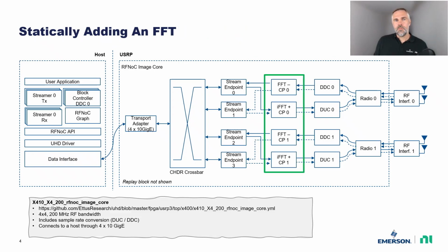So the target FPGA design would look like this. We've added a dual channel FFT and cyclic prefix removal into both receive paths, and a dual channel IFFT and cyclic prefix addition into both transmit paths.